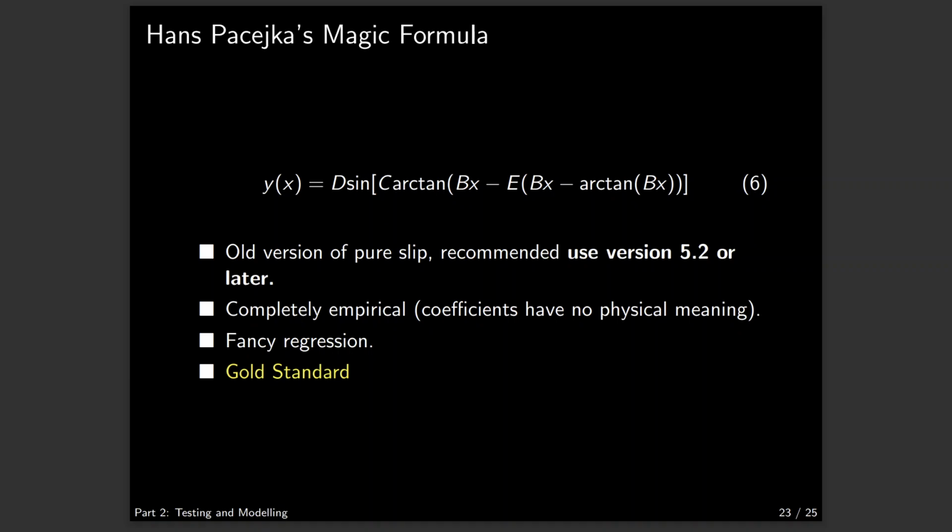Now that we have the tire data, we need to package it into a model that we can use to study performance mathematically. This can be an equation, a Simulink block, or a function. What matters is the ability for your program to identify what force your tire is outputting based on its deformation. The gold standard of this process is the Pacejka magic formula.